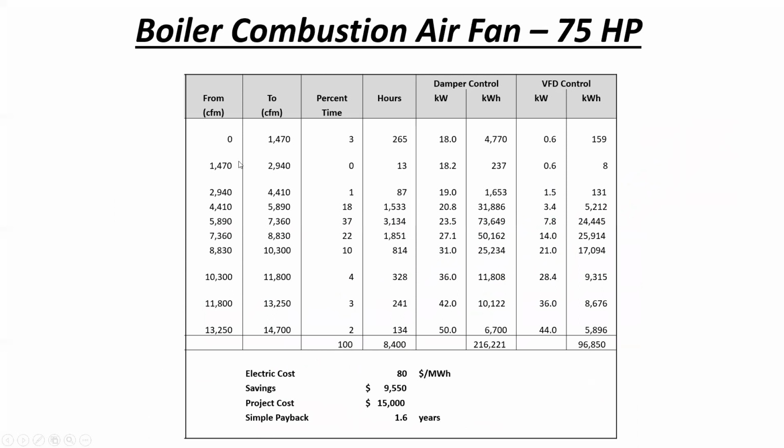Here they collected some measured data that they divided by CFM based on hours, based on percent in time, and compared the kW used with VFD or damper control. They showed a 1.6 years simple payback period, that in less than 2 years it pays for itself for the cost of the installation.